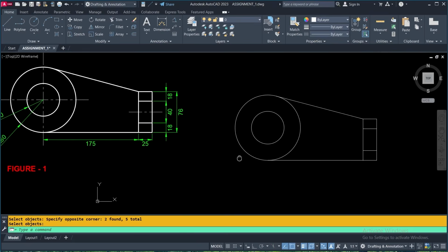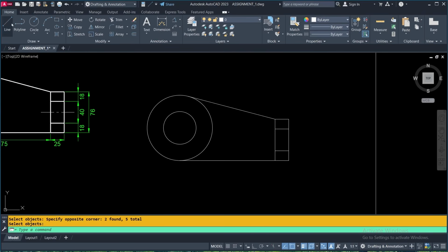Only we have to draw a line here. Though it is a center line, we will draw it as a normal line here. We have not yet learned how to draw a center line. Clicking. Our O-snap is on and O-track is on. So we are activating the O-snap button, then moving to the right hand side. Click here. Now switching on ortho, press F8 or click. Then I am going to the left hand side and click here, then pressing enter.